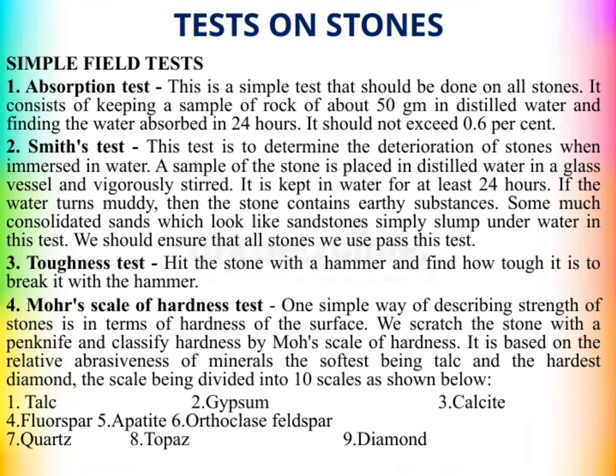Some sands that look like sandstone might slump or disintegrate under water in this test, so it's a good way to weed out unsuitable stones. We want to ensure that all stones we select pass this test for durability.